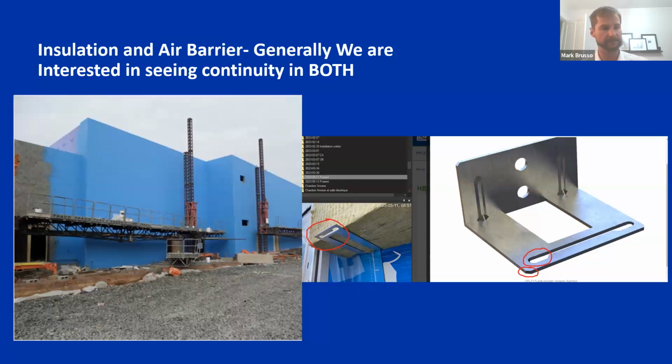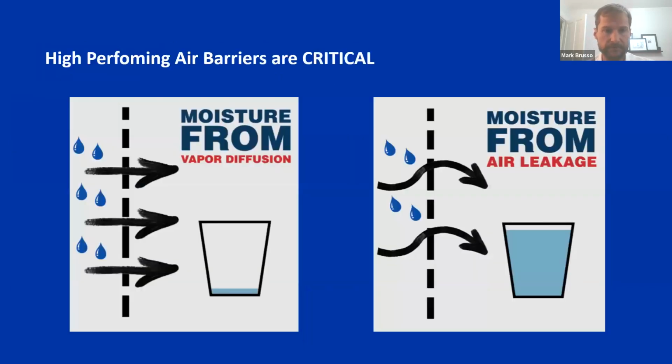I'm confident that some of the audience today is dealing with insulation cavities much greater than even 6 or 7 inches. I've heard up to 12 in certain regions. So growing insulation cavities is definitely a trend right now that I'm seeing in our markets. And everything changes from that point, including our spans, the connectors, our air vapor barriers. So everything is changing now to accommodate these more demanding energy codes.